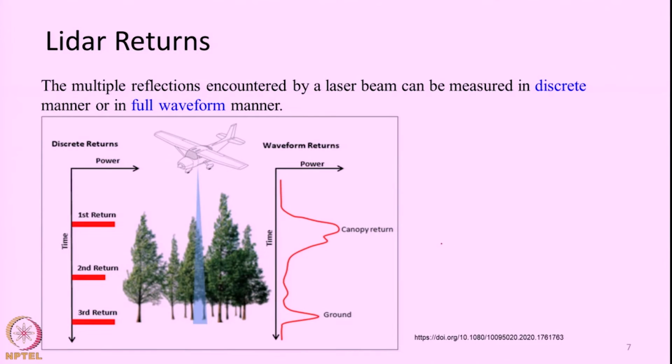Within a footprint, there need not be only one feature with uniform elevation. There can be several features. Let us say you have bare ground without any undulation. Then the single footprint of the laser beam, the entire thing, is going to hit this surface and go back. On the other hand, let us say you are measuring over a land surface covered with trees or vegetation.